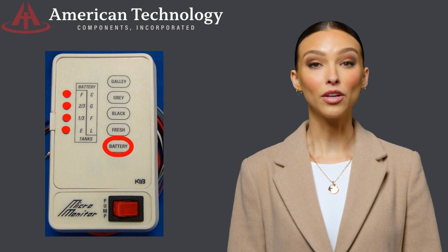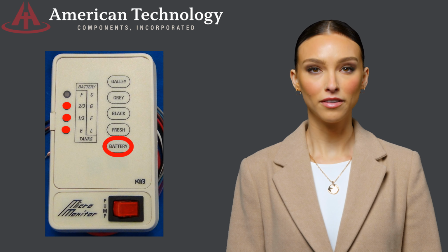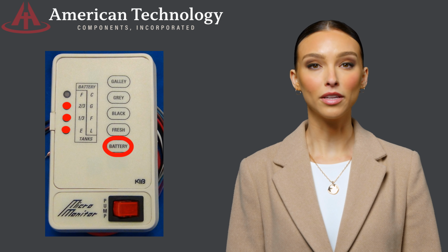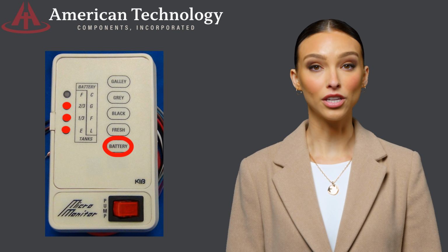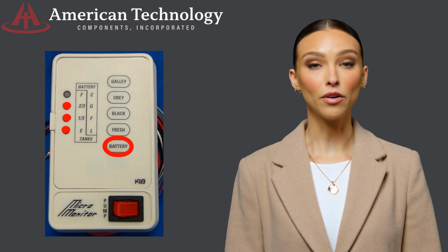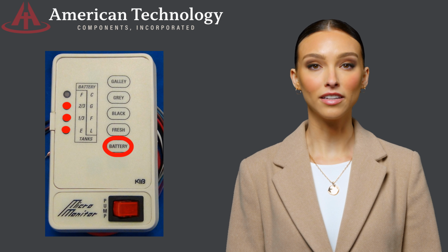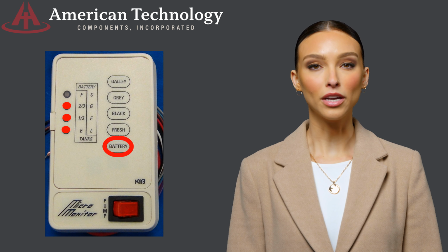To begin testing, you will press and hold the battery button. All the LEDs should light up. If one of the LEDs fails to illuminate, verify adequate battery power. You will need a fully charged battery with more than 12.7 volts. If you do not have adequate voltage, charge the battery and try again. If you have proper voltage and one or more of the LEDs fail to illuminate, then the board has failed and requires replacement. But if all the LEDs illuminate, then you can proceed to test the individual level indications.